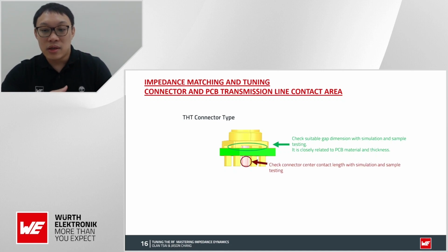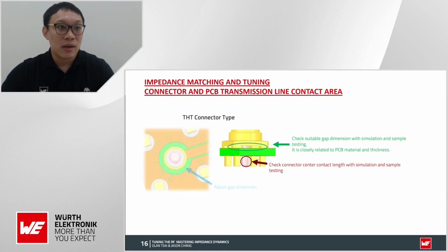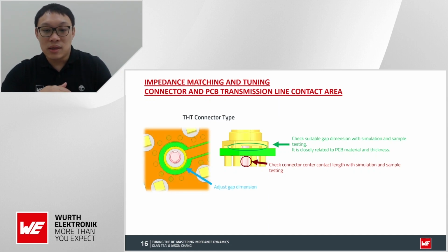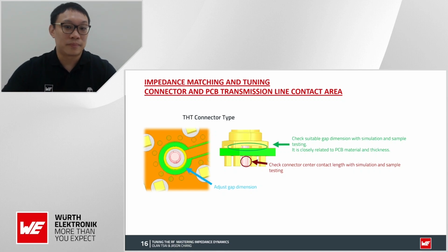And the second one is to check the connector center contact depth with the simulation software, also the actual sample testing. And the third one is trying to adjust the gap dimension where it contacts the center contact and also the PCB.